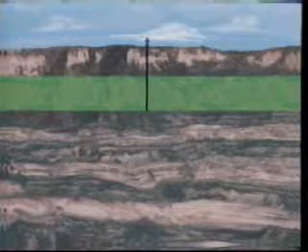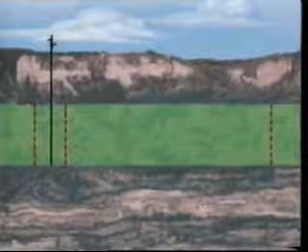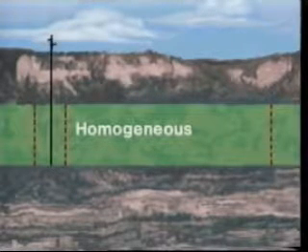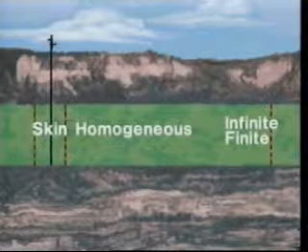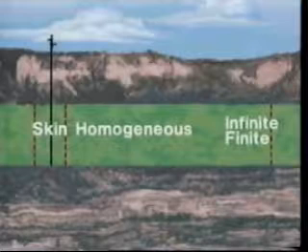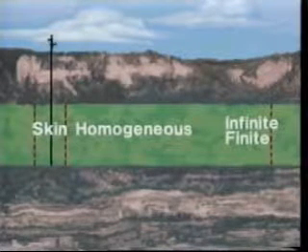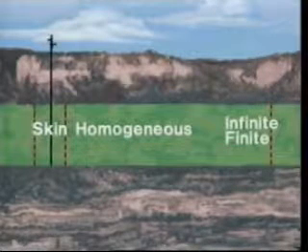The conventional methods are based upon the original Horner and Miller pressure buildup analysis. The reservoir system model is quite ideal. It assumes a homogeneous reservoir structure with skin and may be of infinite or finite lateral extent. Wellbore storage may be present, but it is not analyzed. A few other conditions discussed in Unit 2 are also not analyzed.